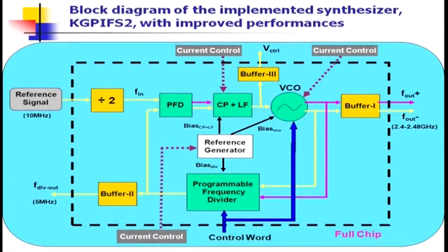If you go to a higher frequency clock, it has much better frequency tolerance, that is, change in frequency because of temperature variation, or noise contribution, for any oscillator. If you buy oscillators from the market, 5 megahertz, 10 megahertz or 20 megahertz, which one will you select? You will always select a little higher megahertz. That will give better noise characteristics than the lower frequency.